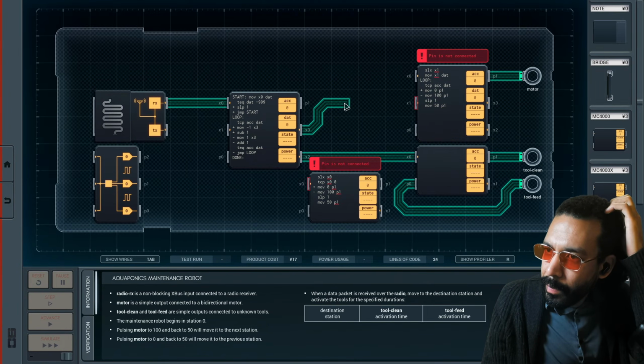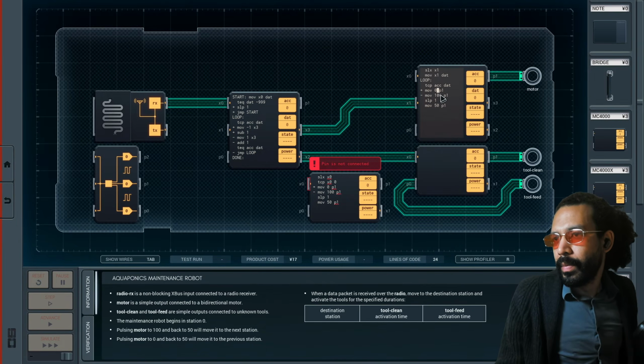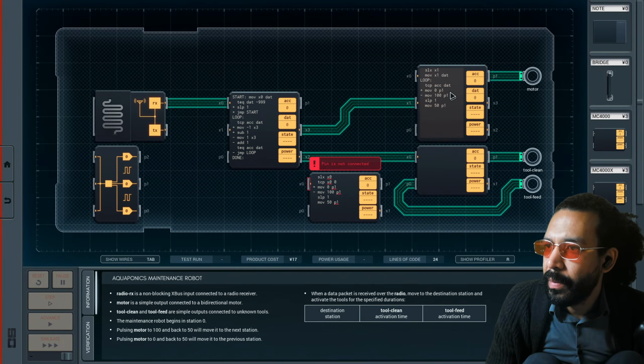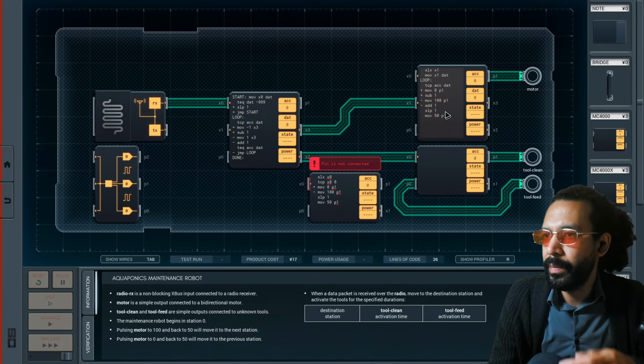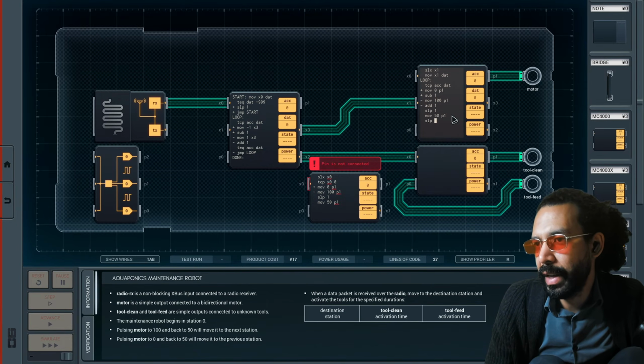Okay. So, when accumulator is greater than data, we move 0 to P1 to diminish it, right? We also sub 1. And when it's less than, we move 100 to P1, which increases it, and we add 1. And we sleep 1, move 50 to P1, sleep 1 again.